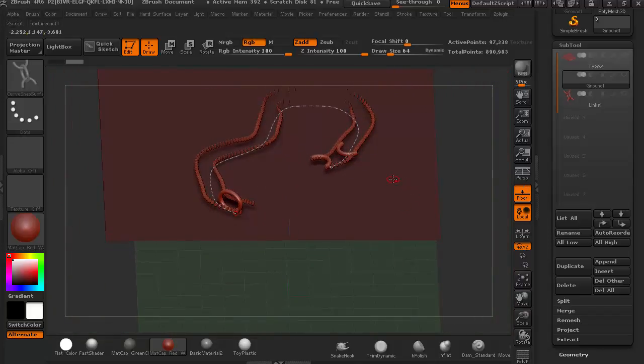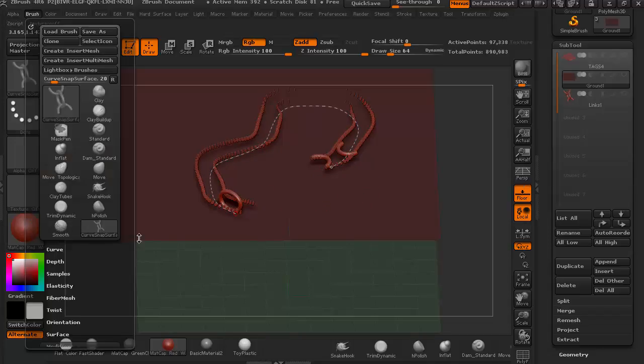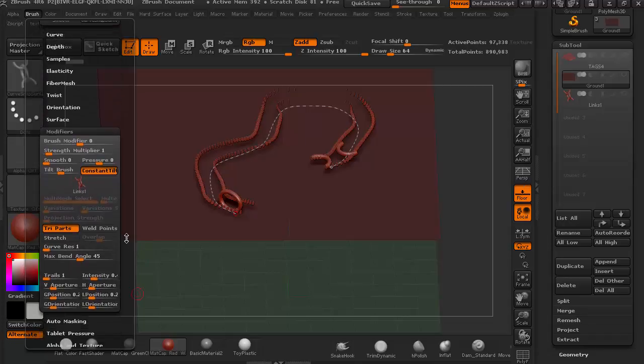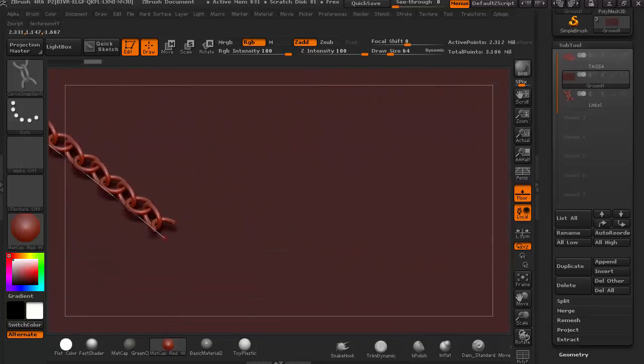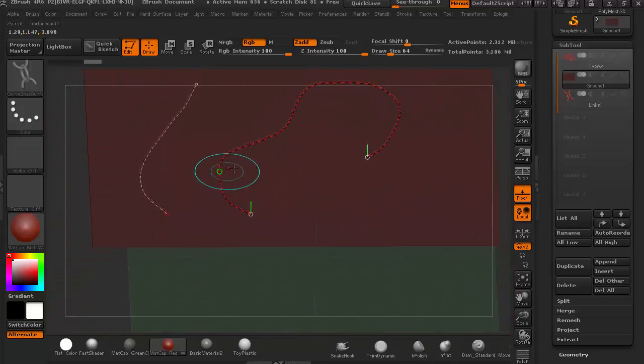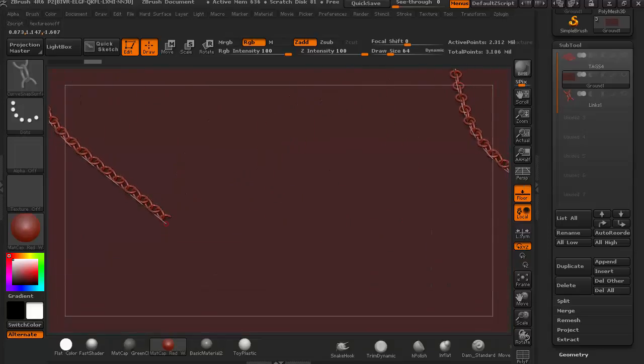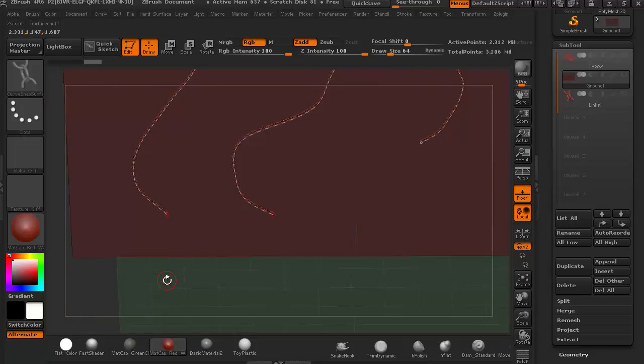The reason this has happened is we need to group our object because it's kind of trying to work it out. If I come down here, you'll see that I've got triparts turned on. It's using more parts to create the curve. So I could turn this off and see what happens then. Now that's a lot more like we expect. That's because we've got the triparts off, and you also see that this is updated to the right curve now. But there might be times when we want to use multiple parts.